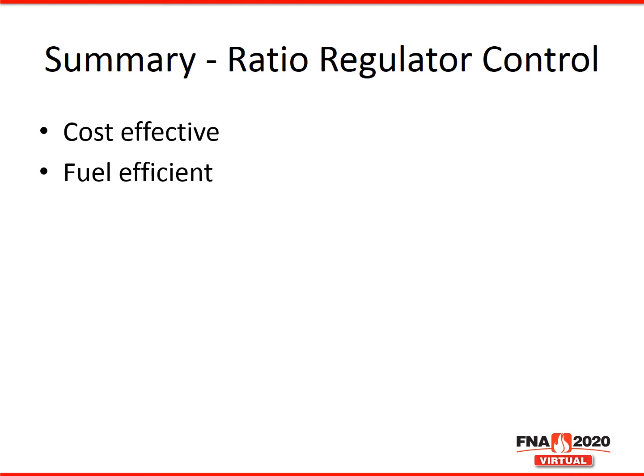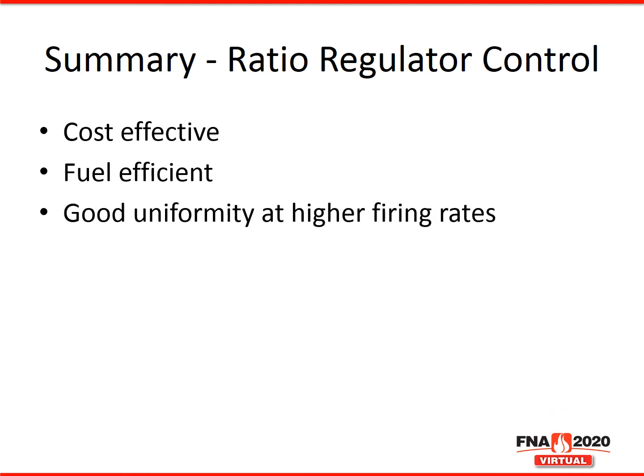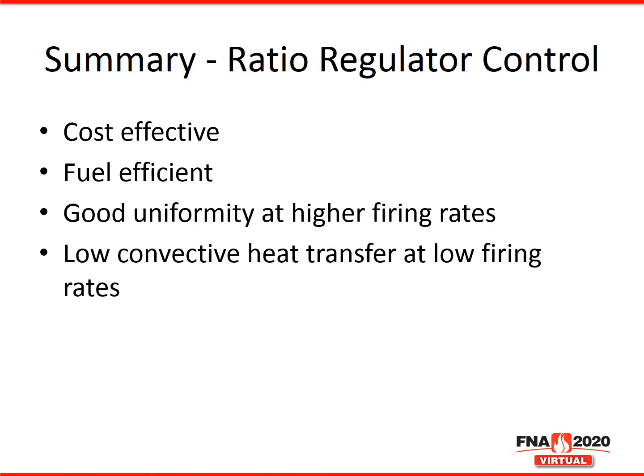Ratio regulator does provide a fuel efficient system, so the running fuel cost of the furnace will be low. Good uniformity can be obtained at high firing rates. The downside of this ratio control is low convective heat transfer at the low firing rates.